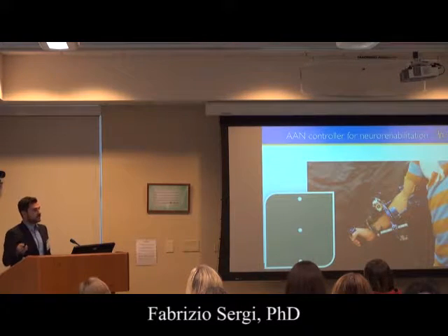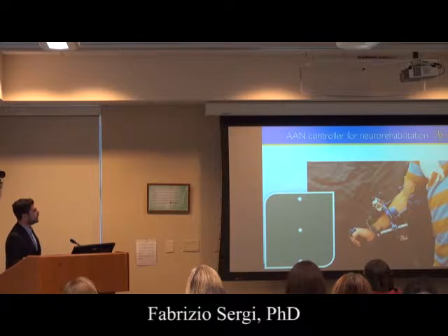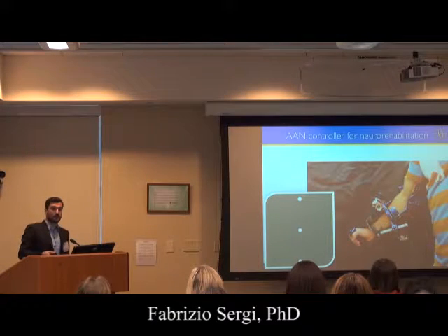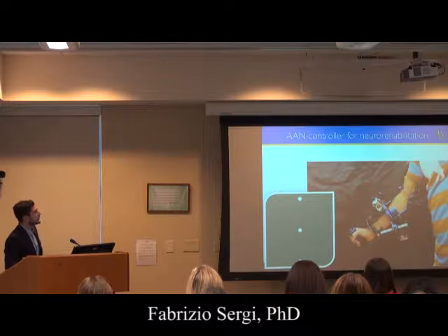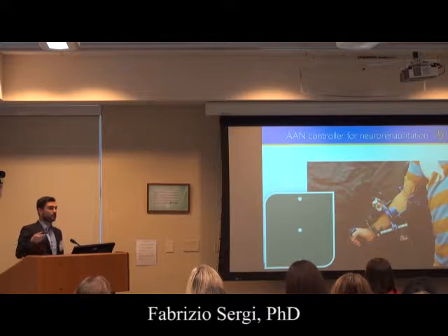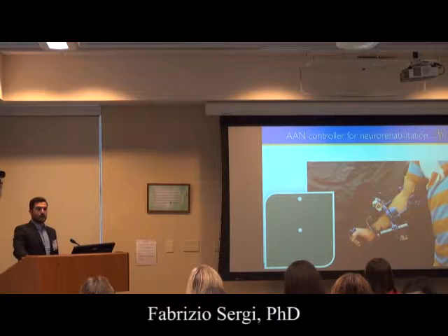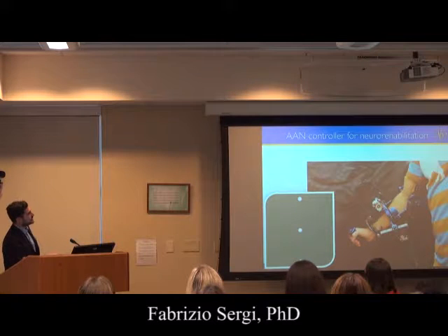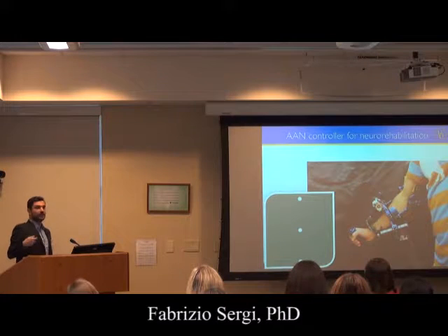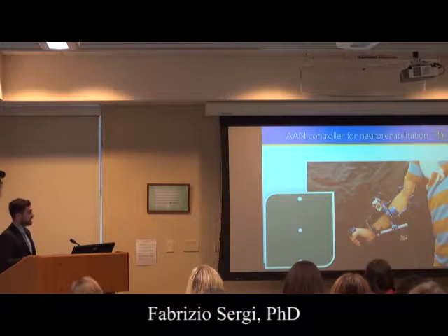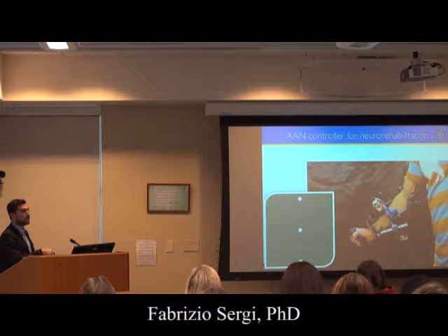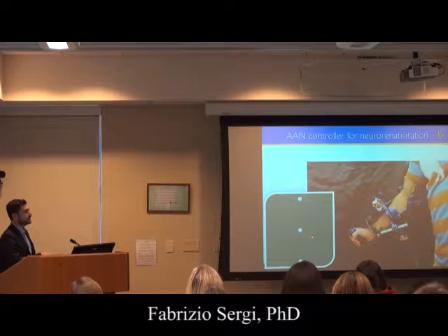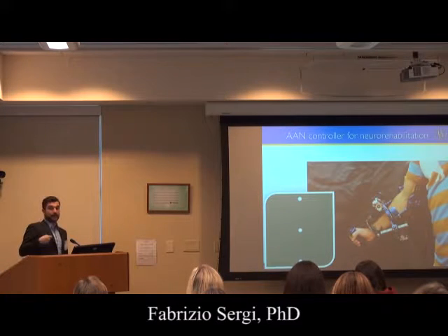So this is a video taken at Rice University a year ago when we were developing this upper arm exoskeleton. It's a 4 degrees of freedom robot, which means that it can assist elbow flexion extension and the 3 wrist rotations. And so you can see that the subject here is interacting, grasping a handle, and then moving his joint. And what he can see is a video game of what he's doing. So there is a cursor that will move across these via points, and so he will have to go up and then down, using one joint at a time.